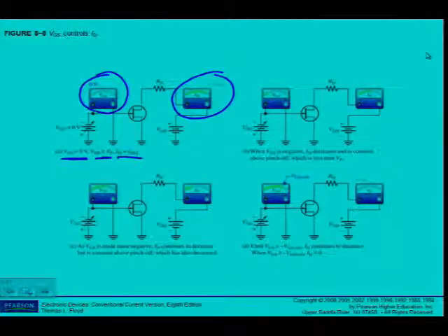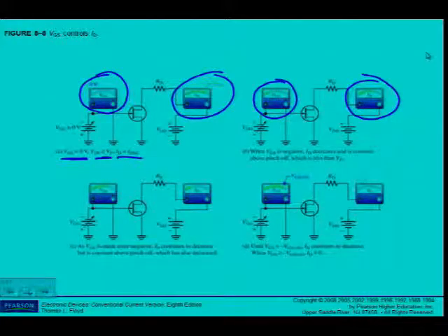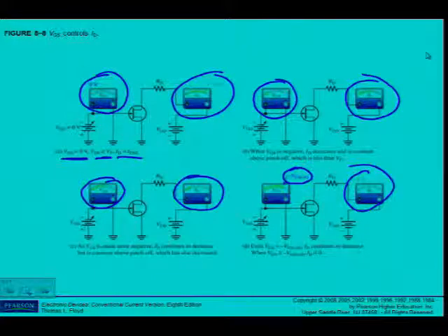Né? Now I start to increase the biasing voltage VGS, and I can see that the current now becomes smaller because the depletion region starts to grow. The channel becomes narrower, and keeps on happening as I increase VGS. Current still becomes smaller up to a point where I reach VGS off. Where is VGS off? That is where the two touch each other, the channel is closed, no current flows through, and I can see on my ammeter that no current is flowing through this device. Alright.